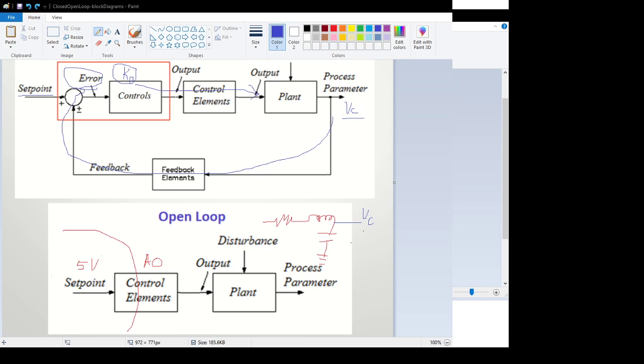So remember, the actual output through the output card is an integer, but control out is a float. Control out is in volts, control out integer is millivolts, so I actually have to multiply by 1,000 to output that. So that is my control system here.